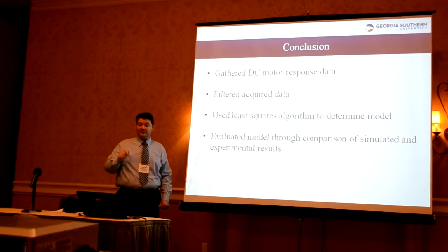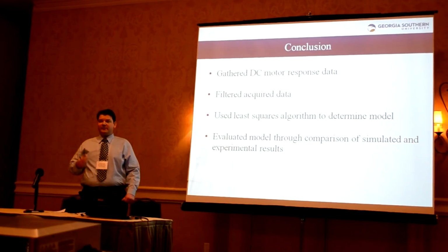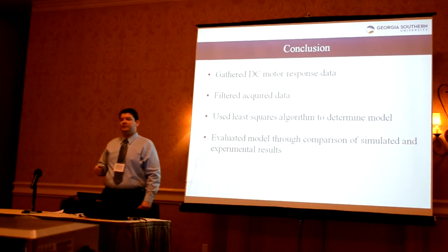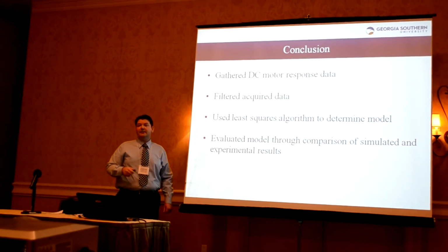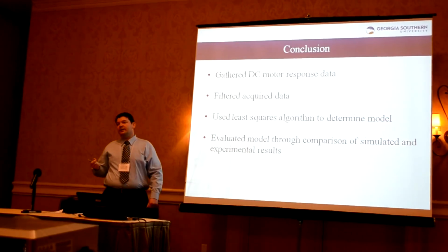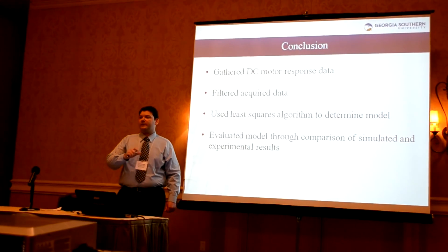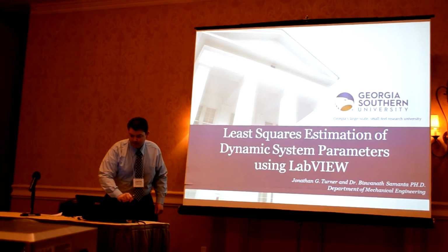What we found on this comparison was that the best response of the simulated system was for the 0.5 Hertz 3 volts peak to peak sine wave input waveform, and it came to be a correspondence of 0.15 volts, which represents 5% of the full scale input range. And that is it.